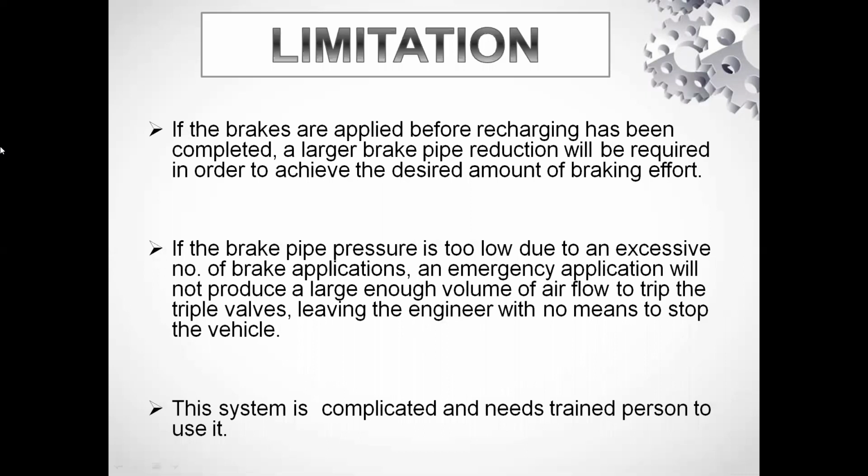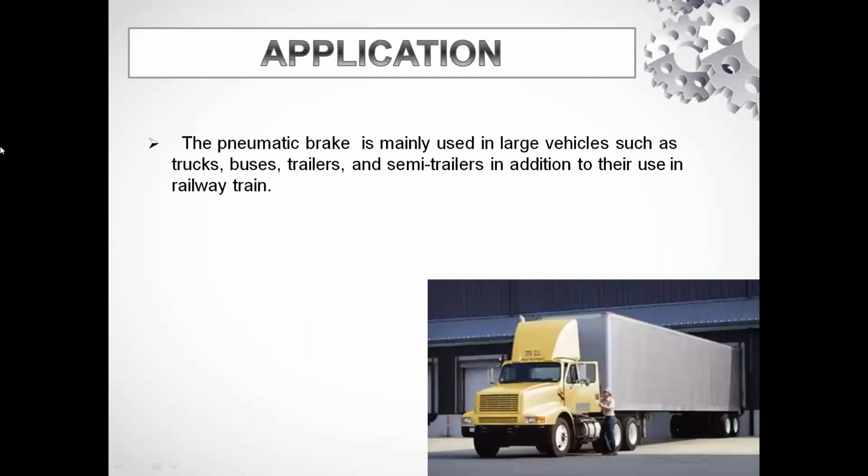If the brakes are applied before recharging has been completed, a larger brake pipe reduction will be required in order to achieve the desired amount of braking effort. If the brake pipe pressure is too low due to an excessive number of brake applications, an emergency application will not produce a large enough volume of airflow to trip the triple valves, leaving the engineer with no means to stop the vehicle. So these are the limitations.